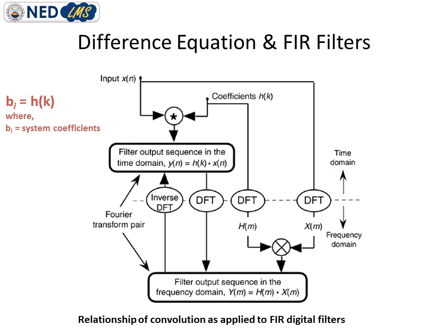So here you can notice that if we are convolving two signals in time domain, then multiplication happens in frequency domain, and we end up with the same results with both operations, whether we are convolving two signals in time domain or multiplying their spectrums in frequency domain. Both are the same. The difference is basically the transformation from time domain to frequency domain.